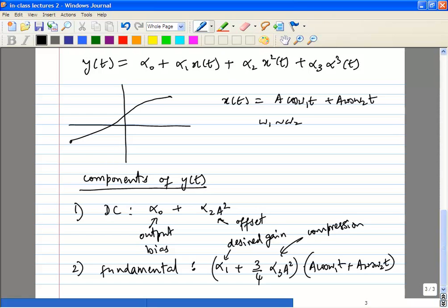So if some amplifier has a characteristic where it is expanding, and then it is coming back, in that case we will take the expanding 1 dB term as a criterion. Normally, the reason you would want to design a gain expansion kind of circuit is because you want to extend out your 1 dB compression point.